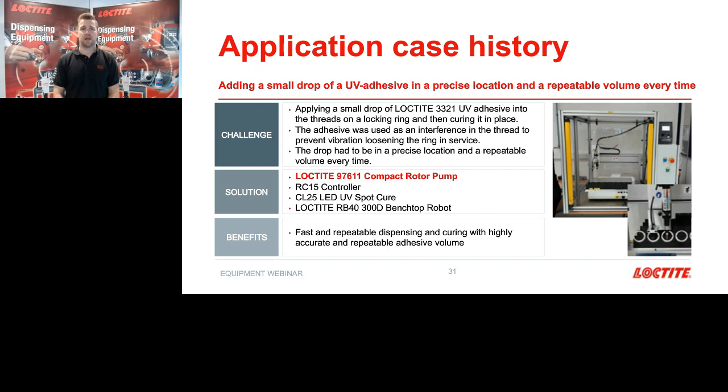And the reason we had to have it accurate, both in terms of size and placement, was that the cured drop of adhesive actually acted as an interference. So when the ring was mated with its other part, it acted as a vibration protection, and it was a safety critical application, so we needed to ensure it was repeatable.